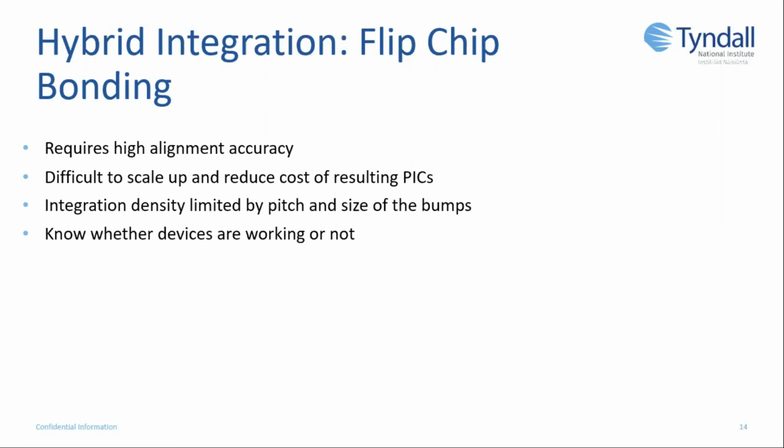However, unlike wafer bonding and like micro transfer printing, you know whether or not a device is working as the devices are finished on the gain chip. So yeah, there's reliability. You know that, okay, I'm flip chip bonding this device to this circuit, and I know it already works. I've already characterized it. So the main issues that will arise after that will be to do with the flip chip bonding, if there is any.